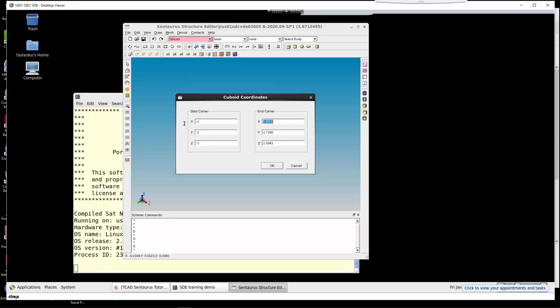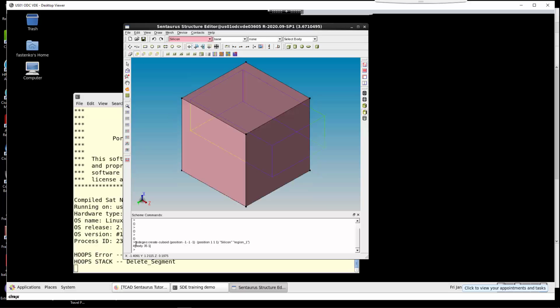Defining a complex device structure involves experimentation, which can lead to errors and even crashes. Performing a long sequence of operations in GUI is often problematic. One way to generate and maintain this script is, after each user interface-based operation, copy an echoed Scheme script command from the command line window to a text editor. After that, edit the script if necessary and copy the script back to the command line window.